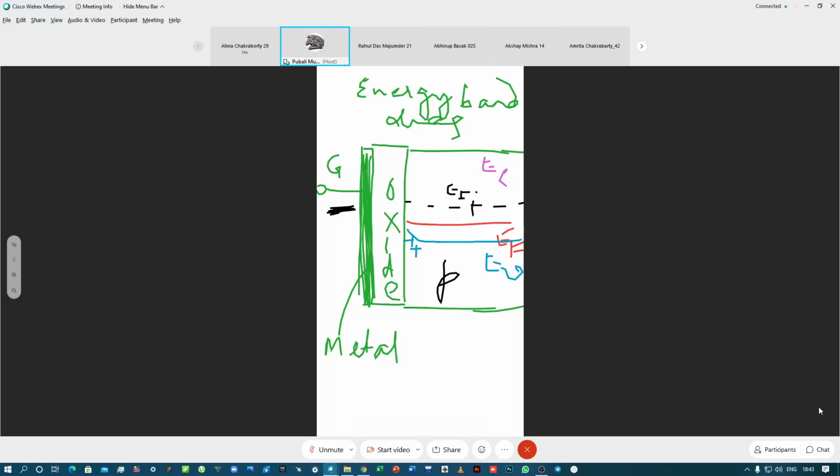you have the bending of the bands in case of your conduction band as well. The conduction band moves up a little bit away from the Fermi energy level, and therefore the intrinsic Fermi energy level maintains its property of being equidistant from the conduction and the valence band. Therefore, it too takes a curved structure like this. So this is band bending.